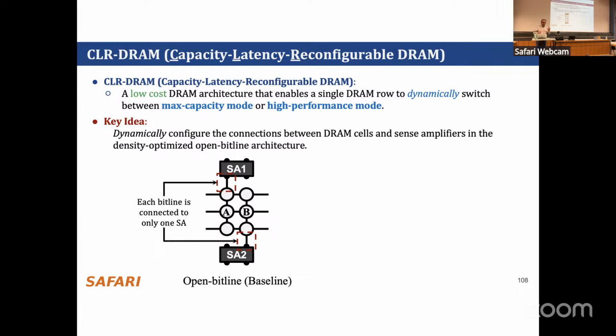And if you remember Ismail's work, functionally complete Boolean logic, we actually benefit from this open bitline architecture to do NOT operation, NAND and NOR, and all these operations that we discussed. When you activate, this bitline, which is connected to sense amplifier 1, is actually a NOT.